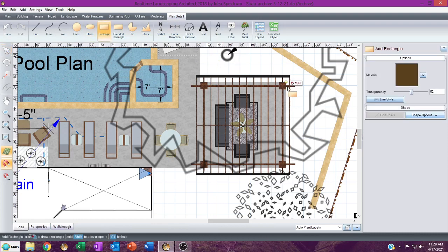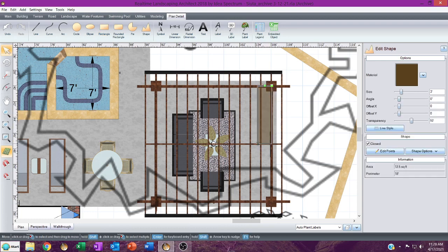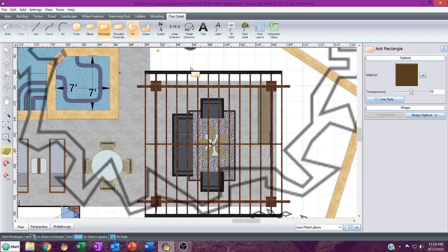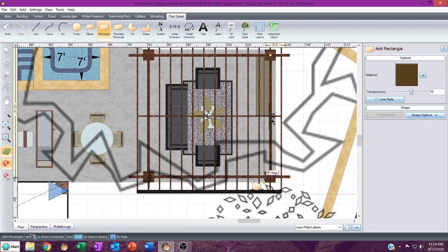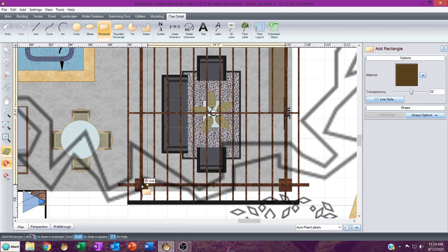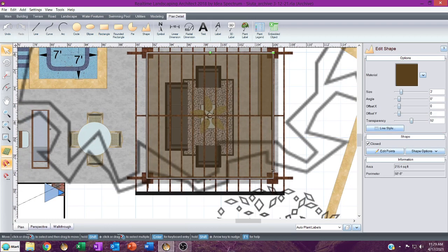And so we're a little bit more exact. What I do on patio covers, I want to make sure that I'm pulling as perfect squares as I can. So I'm going to go from the center of post to my ridge rafter, and then I'm also going to measure from center of post to the center of post. So that's going to give me my span.